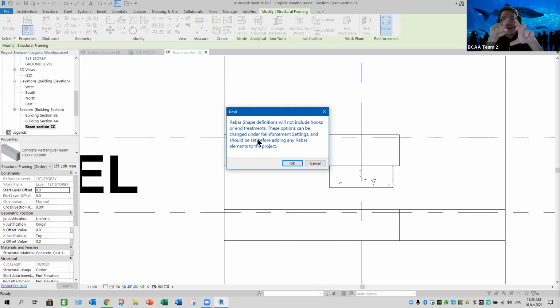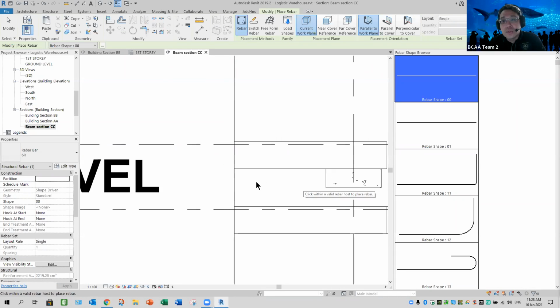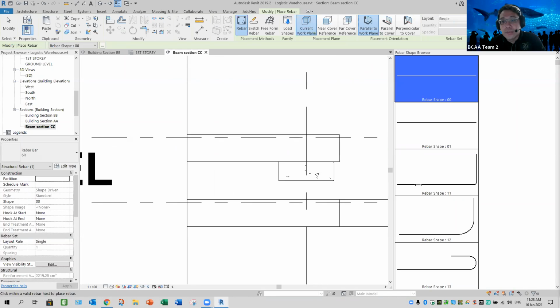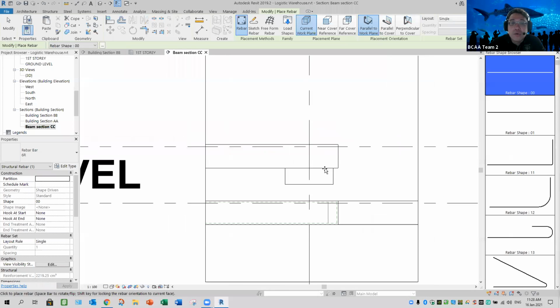It just displays like a box or rectangle shape, which is normally a rebar stirrup. They should have an angle when it comes to the ending. Here it doesn't show. Don't worry, we can still edit. You notice that the tools, the rebar shape will appear. You can resize to adjust it and how you're going to place it.